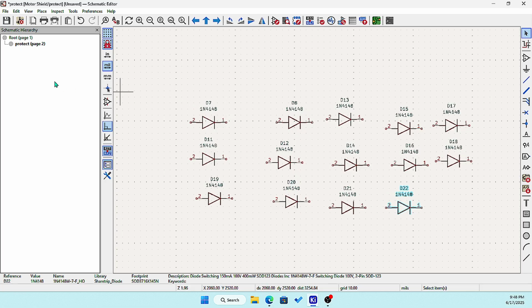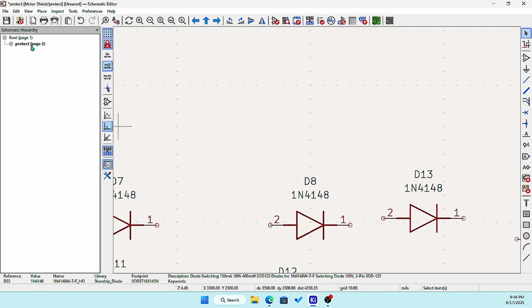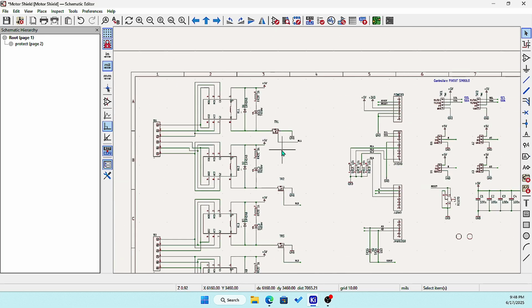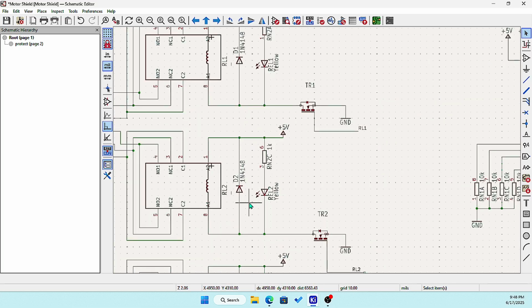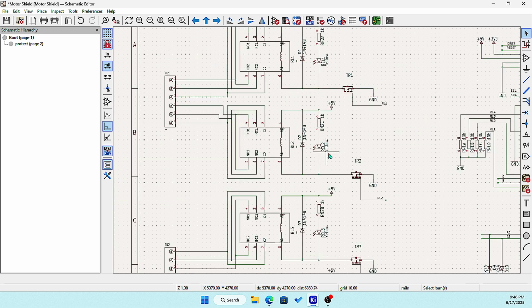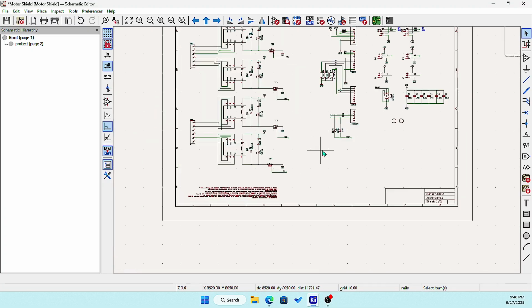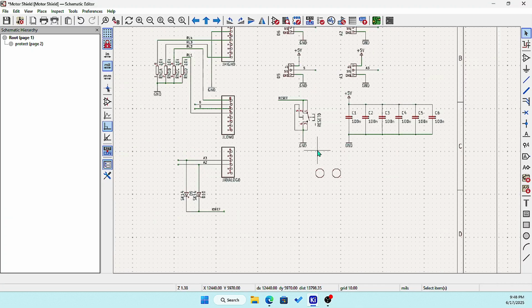So that means if I was looking at this, so I look at the root. So I should have, you see, I have diodes here. That's right. It's renaming the next, it's giving the next name, and it's annotating to the next number. So I should have a D9.